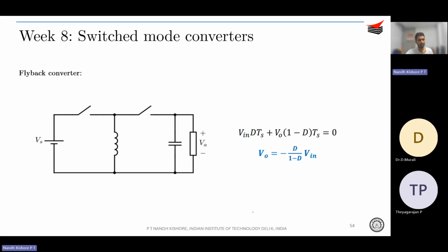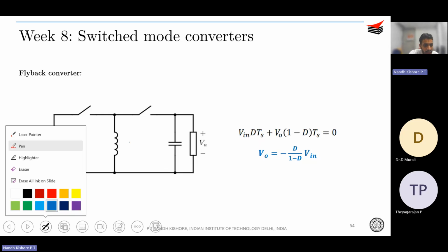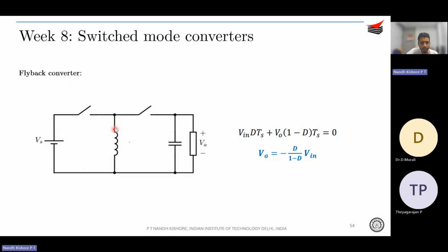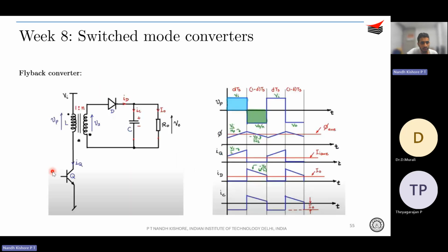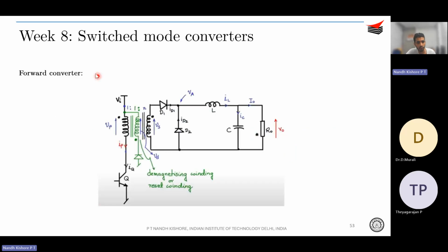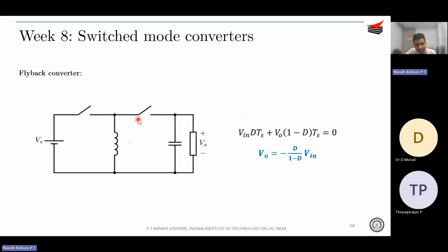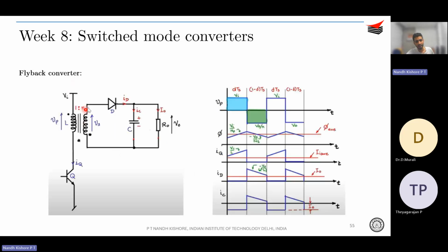Yeah, so we were over here with flyback converters, and as I was saying, it is derived from a buck-boost converter, wherein you have this relationship. So in this inductor part, can I introduce an isolation stage near this inductor? Correct. So that is what we have done over here. Unlike the forward converter, where you have a separate inductor and the isolation is provided by a transformer, over here you understand that this entire inductor is being replaced by a transformer, correct?